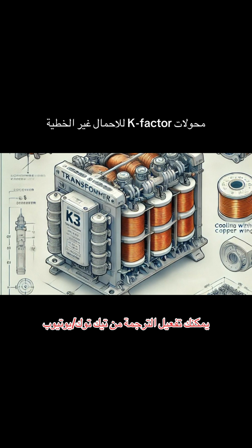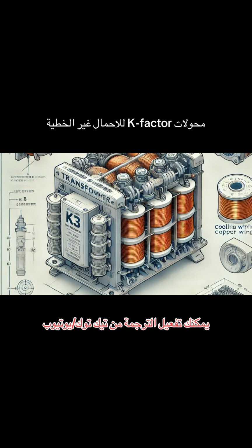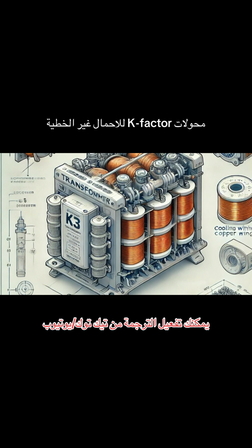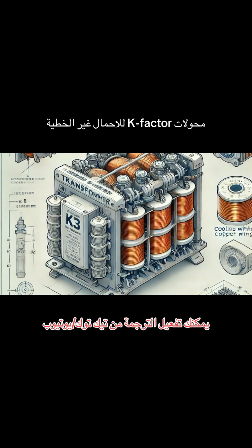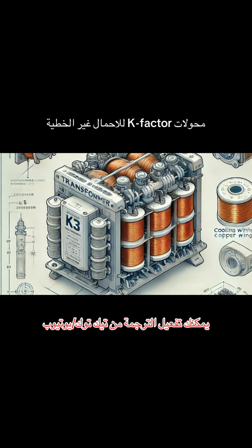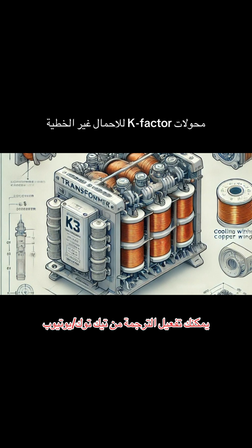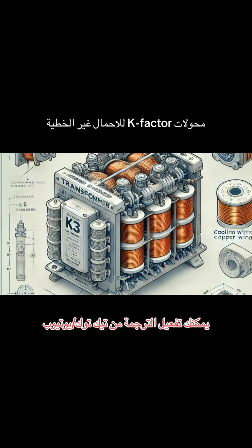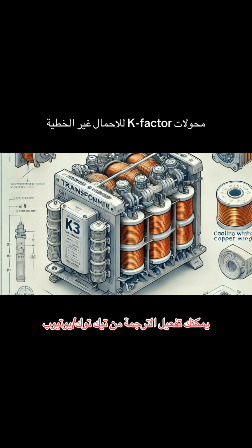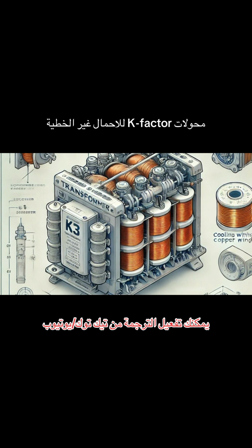And the paper gives a really good example to illustrate this. Imagine you have just 1 amp of this third-order harmonic current on each of the three main power lines, the phases. You end up with a whopping 3 amps of that 180 hertz current all flowing on that single neutral wire. Wow, so it concentrates there. Exactly. It's this hidden accumulation. Now, here's the contrast. Under normal conditions, with older, purely linear loads, think old-school incandescent bulbs or simple resistive heaters, that neutral current is typically super low, almost zero. Oh, okay. That makes sense.